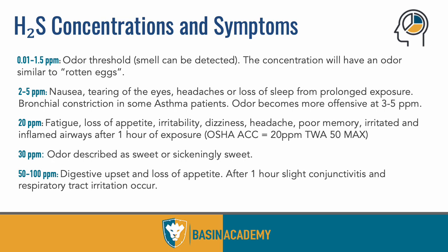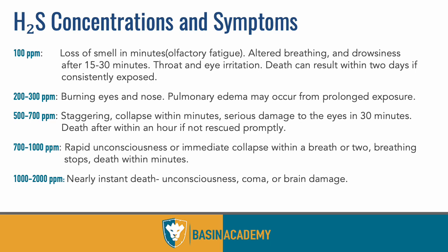Now, at 100 parts per million, that's what we consider the IDLH, or the immediately dangerous to life and health. And I'll get into that in a little bit, but that's where we're going to start to see some more permanent damage from the exposures at those concentrations. So above 100, between 100 and 1,000, depending on who you are, it's going to affect you differently, but that's where we start to see unconsciousness, the lungs starting to fill with fluid. And at 1,000 parts per million, we call that the DRT, which is not an OSHA acronym. It stands for dead right there. So keep that in mind. DRT, not a real thing, but 1,000 parts is pretty much where it's game over for everybody, which is still, again, 0.1% part per million.